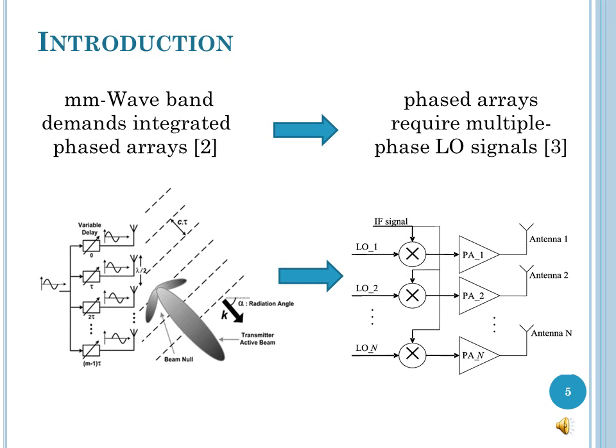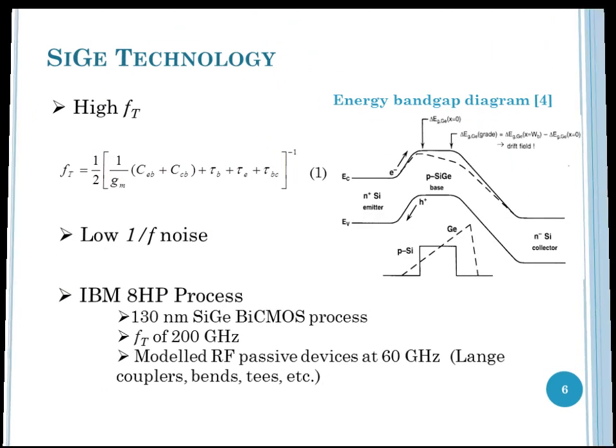To minimize the RMS phase error in the output of the integrated phase shifted VCO, a low phase noise VCO is required. In addition, the particular requirement of an oscillator in any communication system is the low phase noise of the oscillator. This is because the channel spacing is constrained by the phase noise. Hence, this research also targeted the improvement of phase noise performance of VCOs, particularly at 60 GHz, by studying the phenomenon of phase noise generation. I focused on analytically modeling the phase noise to optimize the design performance by identifying the high impact process or design parameters.